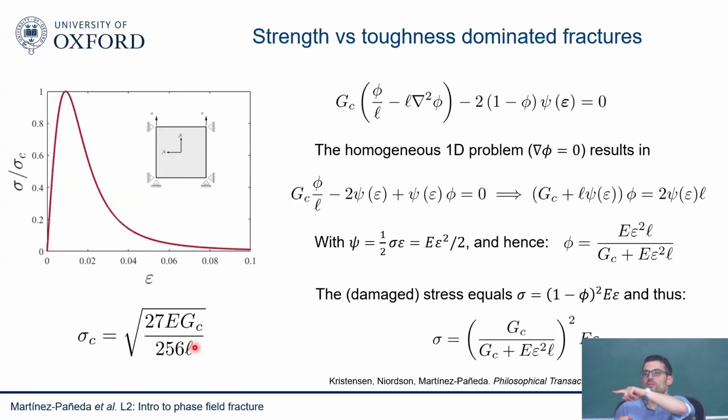If you think of the strength, imagine that you have stresses ahead of your crack. Your stresses are going up. When do you start seeing macro cracking? Normally when your stress reaches some sort of critical strength, then you start seeing this macro cracking. I think I get where you're going. There are other phase field models which are trying to decouple the length scale from the strength, and some of them are quite heavily applied to concrete, so we'll discuss them later on. It's more what we call phase field cohesive models. I have a slide about those things.